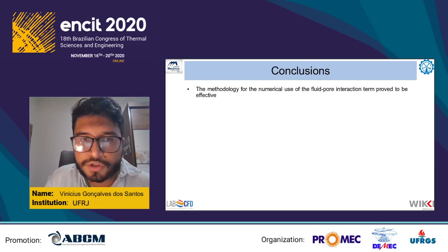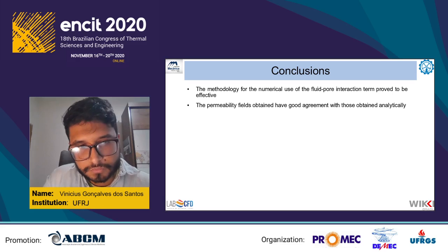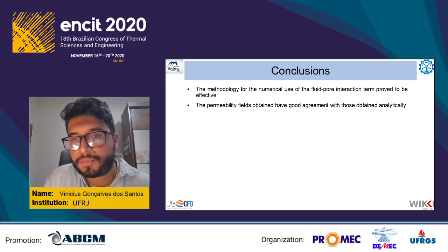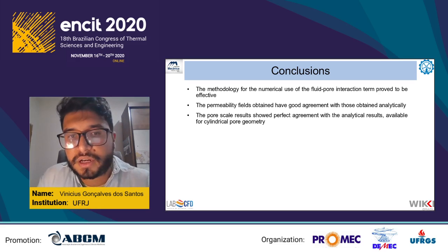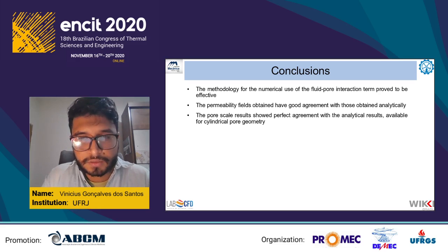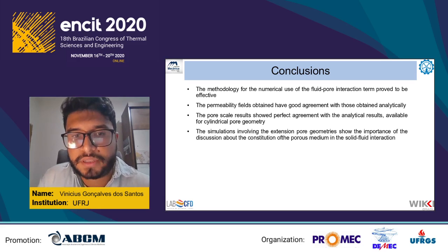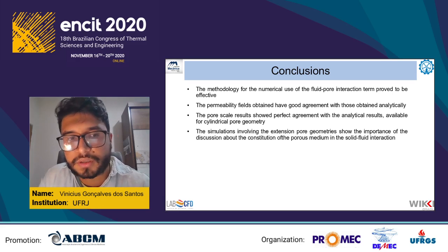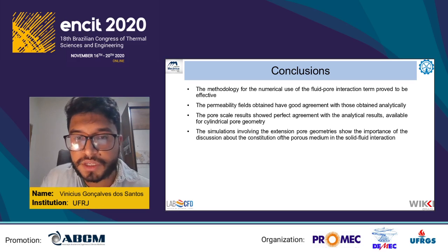Conclusions: the methodology for the numerical treatment of the fluid-pore interaction proved to be effective and promising. The permeability fields obtained have good agreement with those obtained analytically. The pore scale results showed perfect agreement with the analytical results available for cylindrical pores, and the simulations involving the extensional pore geometries show the importance of the discussion about the constitution of the porous medium in the solid-fluid interaction.